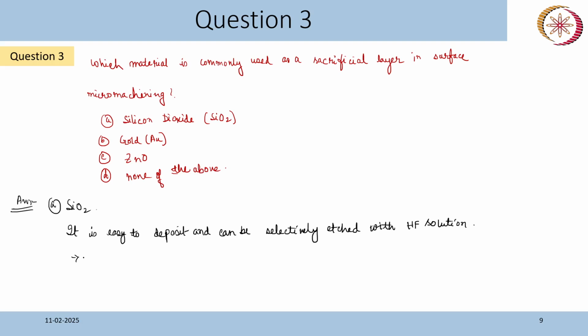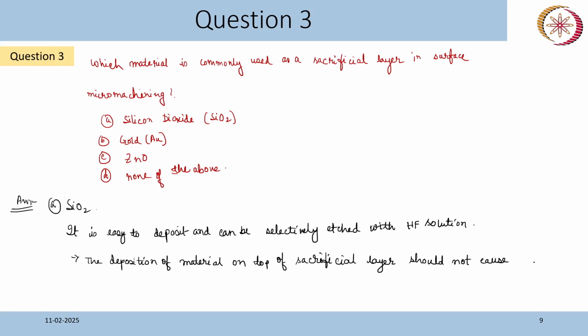The criteria for selecting a sacrificial layer is that the deposition of material on top of the sacrificial layer should not cause the sacrificial layer to melt, dissolve, or crack.